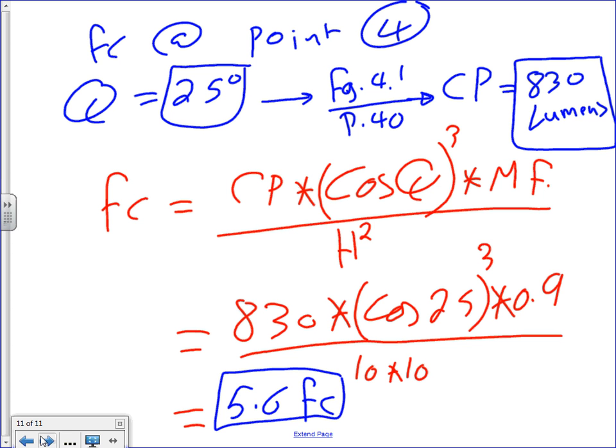Okay, so that's all I have. There's a couple of rules of thumb, guys, at the end. For example, a 4-lamper like this one will, to get you 75 foot candles on average, with the 4-lampers, not 3-lampers, 4-lampers, will cover 75 square feet. One of them will cover 75 square feet. So there's a couple of rules of thumb. Luckily, we have visuals. We don't have to use a whole lot of rules of thumb for these. Okay, so that's basically, we'll wrap up chapter 4, my friend.